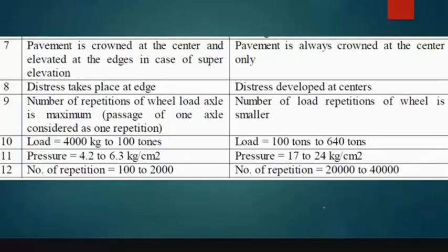And distress takes place at the edge in case of highway pavements. But in airfield pavements, distress will take place at the center, because there are center wheels and side wheels. So maximum distress will be at the center in case of airfield pavements. And